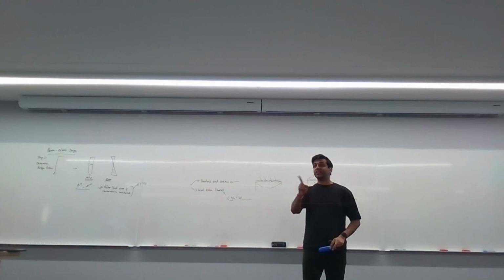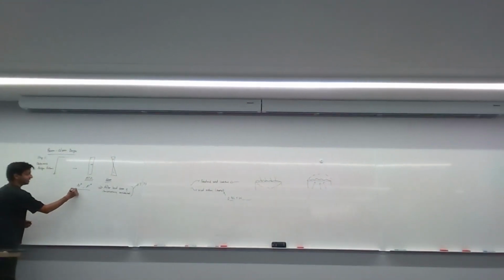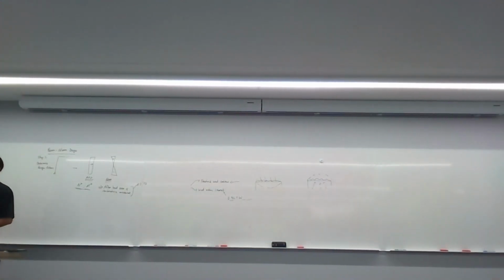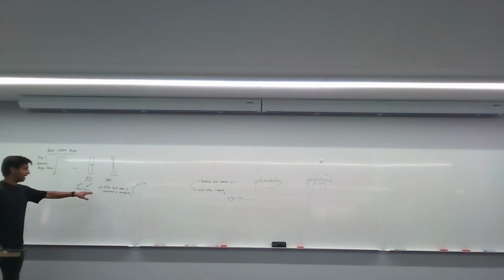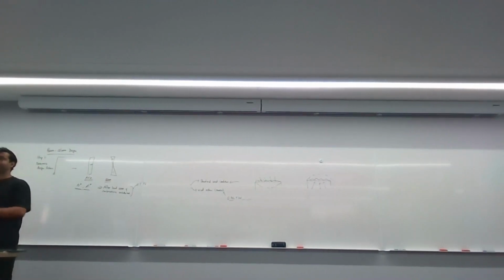Now another important thing that I want you to remember is when you're collecting these forces, when you're collecting N star and M star, please note that both N star and M star have to be from the same load combination. Okay, so I'll give you an example. Let's say in one of your load combinations, you had N star and M star being a certain value. And another load combination, you had another N star and M star.